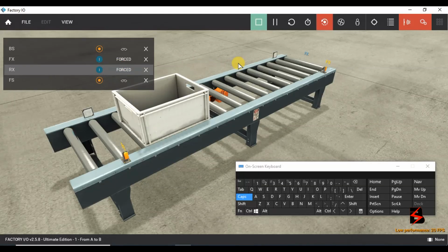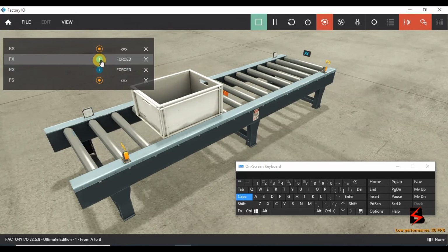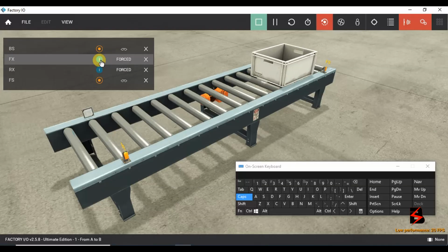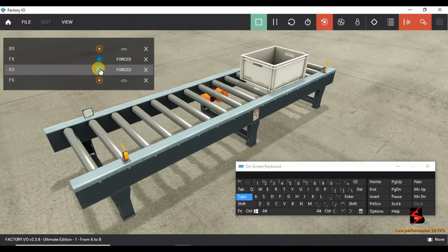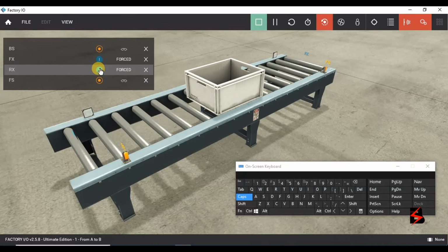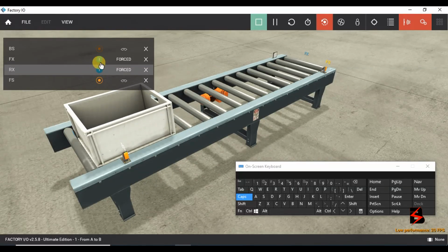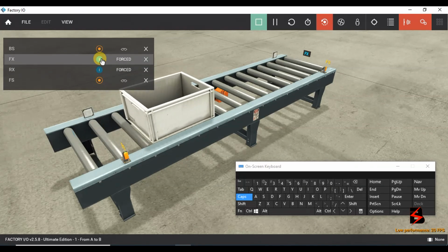But when in automatic mode, you are going to have start and stop buttons, so that when you press start, it is going to go forward. When it reaches the forward sensor, it stops for something like 1 second, then it comes reverse. Also, when it reaches the reverse sensor, it stops for something like 1 second, again it goes back forward.